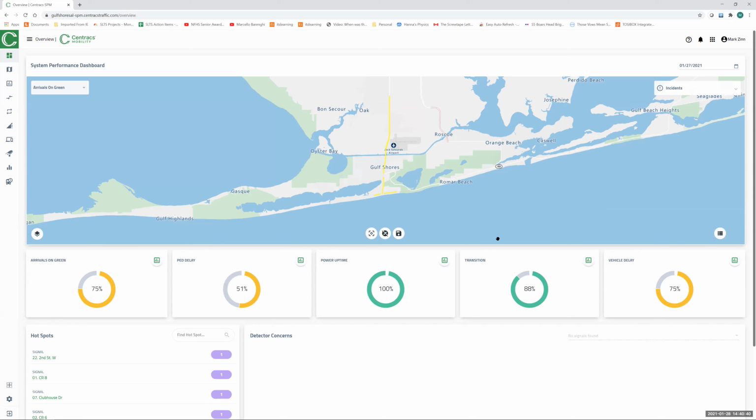If you decide that traffic responsive is the level you want to use, then this will definitely give you an analysis tool to see when those studies need to be redone. Most agencies, again, it's supposed to be 3 to 5 years. I've seen agencies that don't run the new timing studies for 10 years, and it's way out of whack by the time it's done.